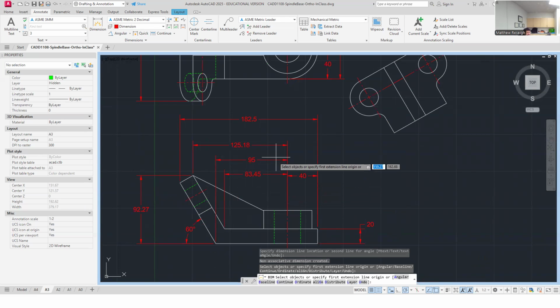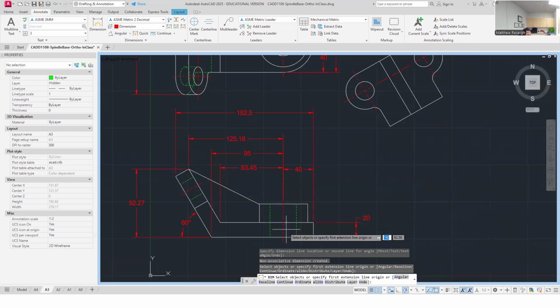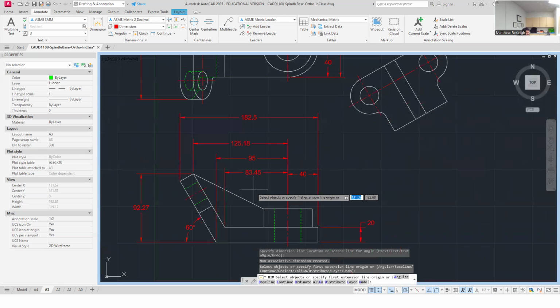So you can say I'm just starting to stack up dimensions, pulling off this. Somebody that knows how to read prints would look at that and say, this must be a datum, this is a control. When I see that on your drawings, when I know that you're pulling from the same point, I'm like, they're starting to establish datums, controls. So that's good. You should start to see these stack ups of dimensions coming from, sometimes, the best part features or datums to pull dimensions from.